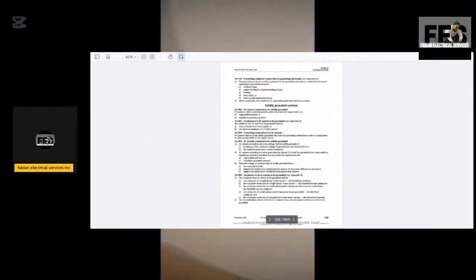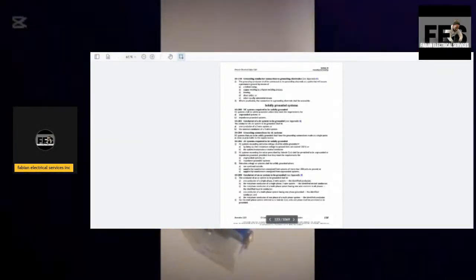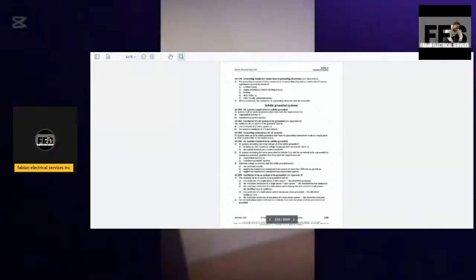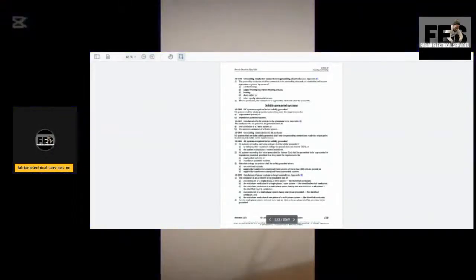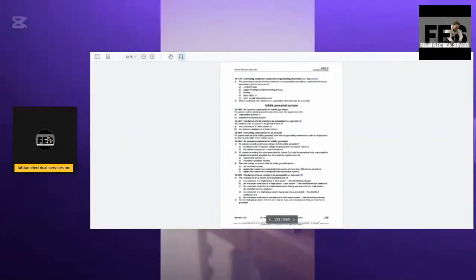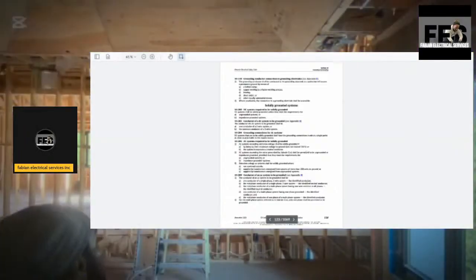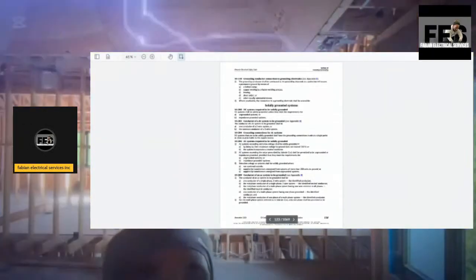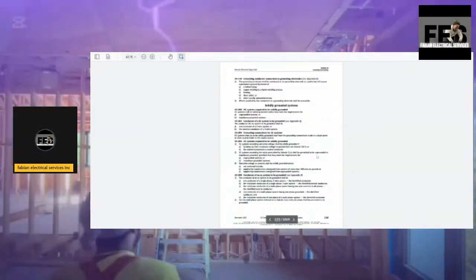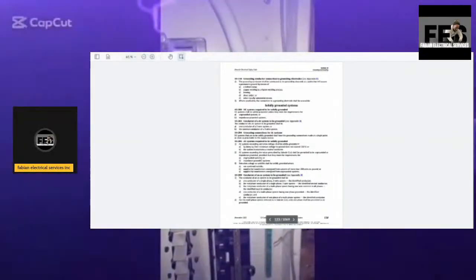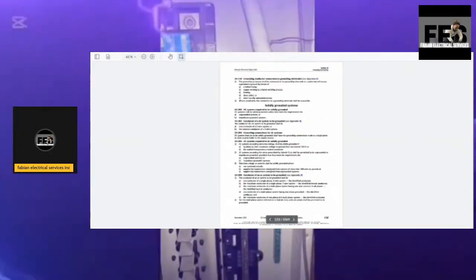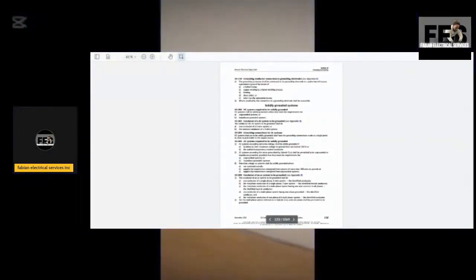AC systems required to be solidly grounded. AC systems exceeding extra low voltage shall be solidly grounded if, by doing so, the maximum voltage to ground does not exceed 150 volts or the system incorporates a neutral conductor. AC systems exceeding the value prescribed by sub-rule 1 shall be permitted to be ungrounded or impedance grounded, provided that they meet the requirements for ungrounded systems or impedance grounded systems.